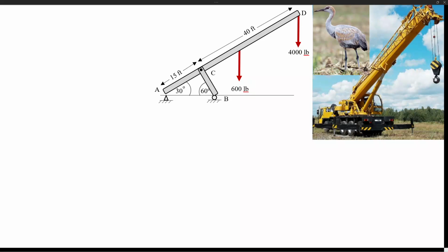How to find reaction forces by applying frame techniques, the analysis of frame techniques. Now, so far until this point, you have seen that one reaction is a pin connection or hinge connection. Another reaction is a rolling contact or frictionless surface. And that gives you only three unknowns.